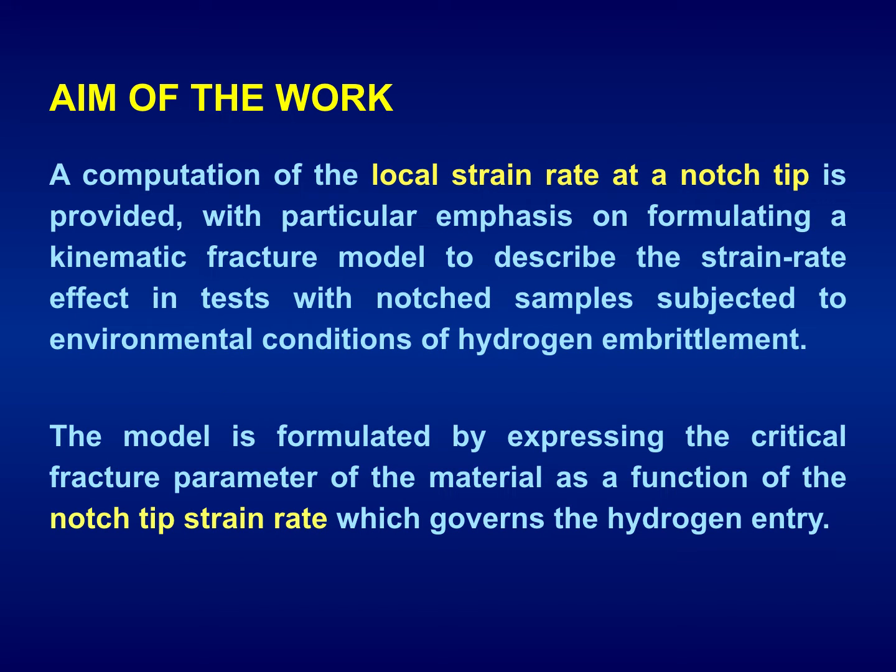Then the aim of the work is a finite element computation of the local strain rate at a notch tip, with particular emphasis on formulating a kinematic fracture model to describe the strain rate dependence in tests with notched specimens subjected to environmental conditions promoting hydrogen embrittlement or hydrogen-assisted fracture.